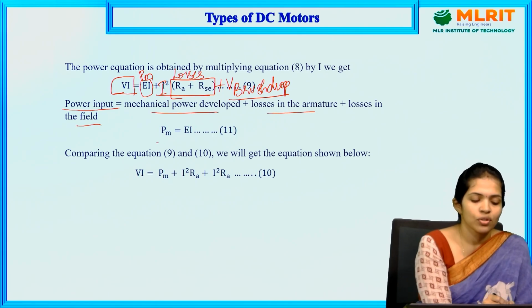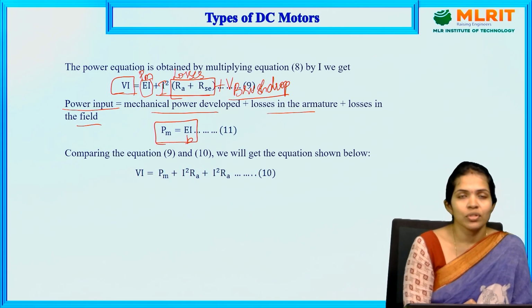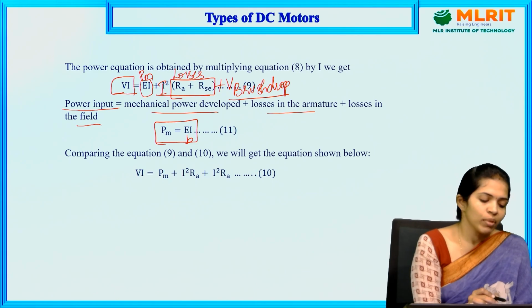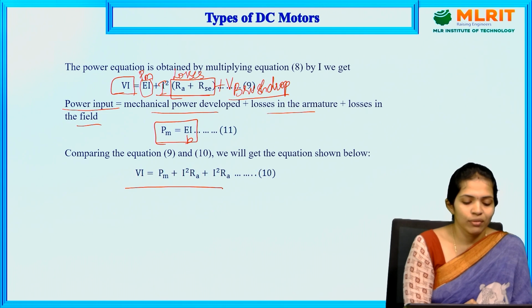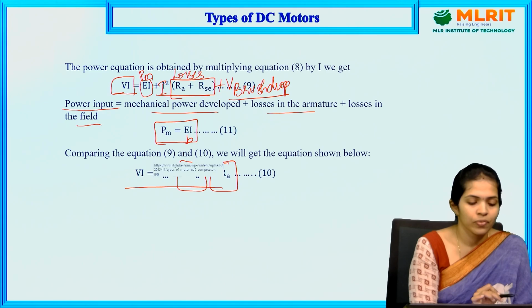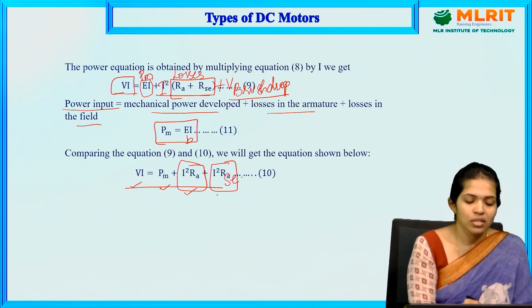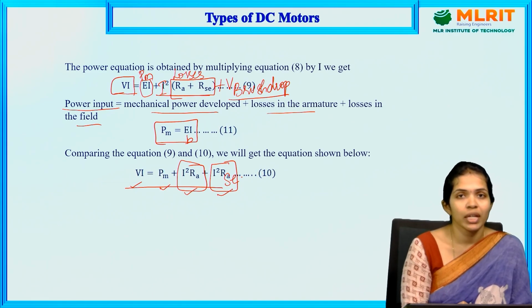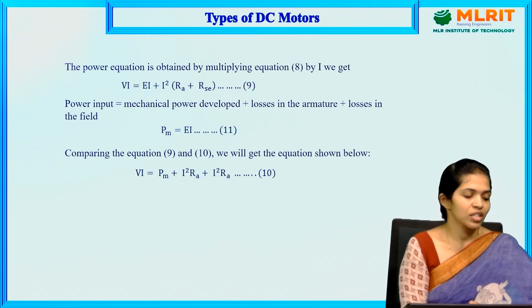and the field. So from here the mechanical power developed will again be EB into IA, the back EMF developed in the armature conductors, multiplied by the current flowing in the entire series circuit. So comparing equations 9 and 10, we get the losses. This we can write as I square RSC. So electrical input equals mechanical output plus the losses occurring in both the armature winding and the series field winding. This is about the series motor and the respective voltage, current and power equations.